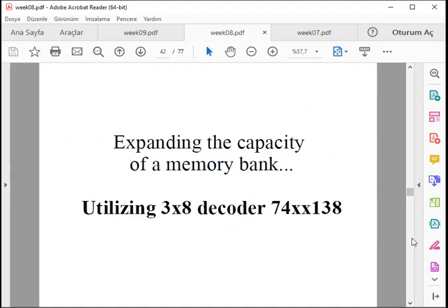So these are good self-study examples as well. I may be a bit quick, but if you self-study each diagram in detail, this is a very straightforward and algorithmic approach. You can understand it very easily, and you can also scale up to gigabytes of memory or many banks. All you have to think about is, first of all, enabling, then decoding, then identifying the addresses, and control pins like read and write. That's it.